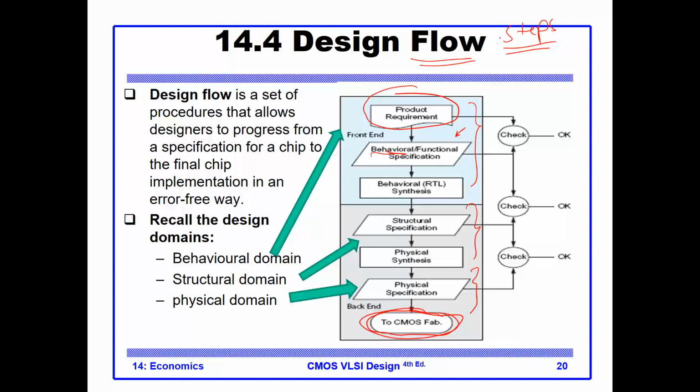It's not that we ignore this completely, but the emphasis is more on the behavioral, functional specification, and then we go to the behavioral RTL. We do the synthesis, then the structural specification, the physical synthesis, and the physical specification, and then we end up with the tape out.